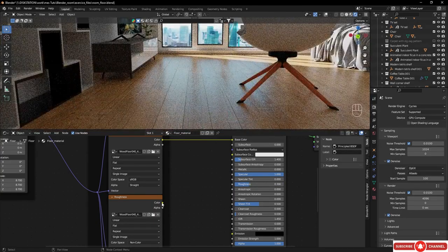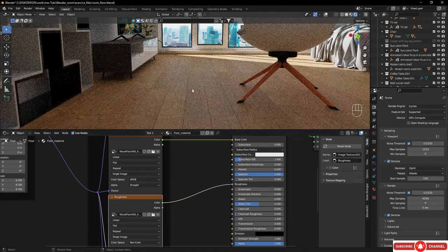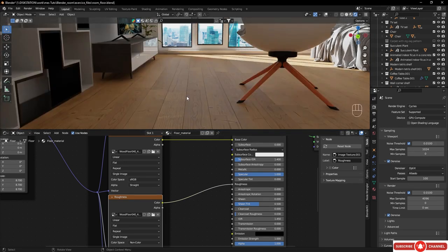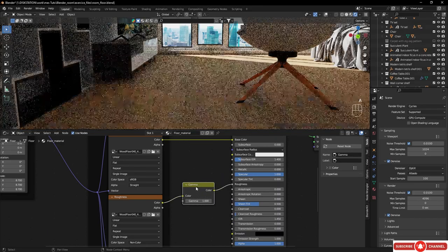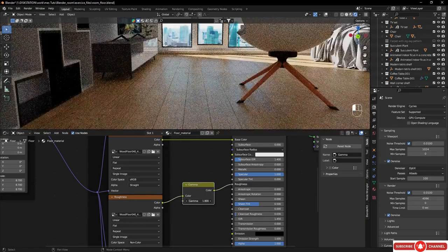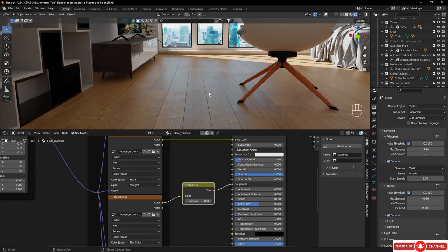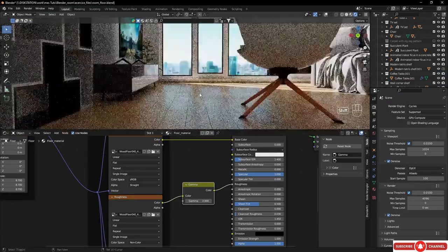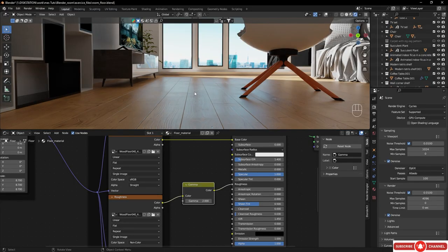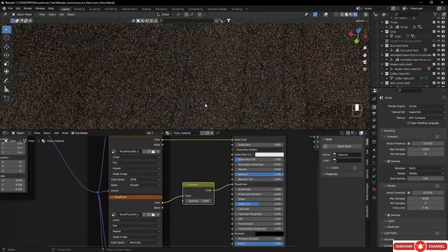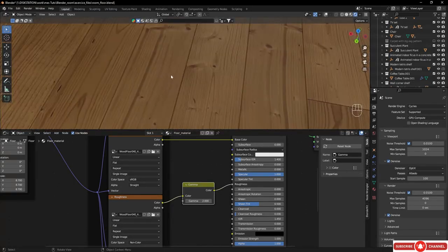And when we plug here the roughness texture, it's rather worn. If we wanted to make it smoother, what we're going to do is add, Shift A, a gamma. I'm going to plug it here. If I increase the gamma, as you can see, it's going to be more shiny. You will see it even more if you have a grazing angle like that. This is a Fresnel effect. And you can see it looks very shiny, whereas if you look just this way, it's less reflective.